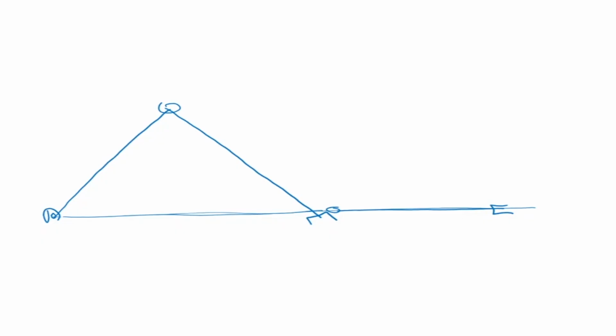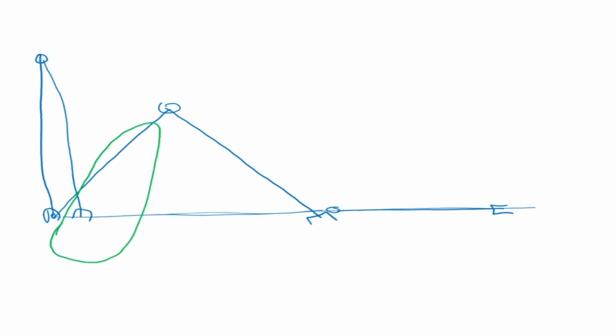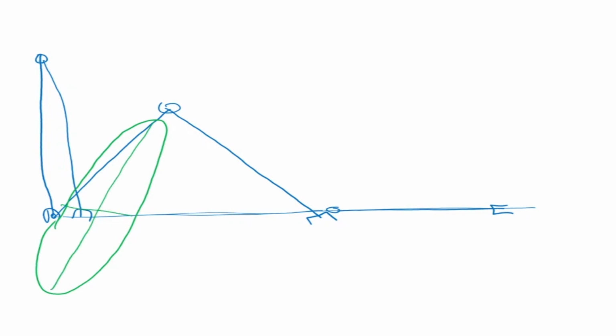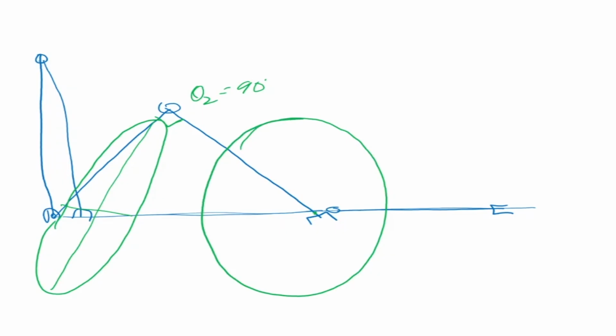Now, as the variation of theta 1 and theta 2 takes place, what is happening? There is an ellipse like this. This is my major axis, that's my minor axis. Towards the center of the workspace, when theta 2 is 90 degrees, this ellipse will tend to become circular. So this is my sigma 1, sigma 2, major axis, minor axis.